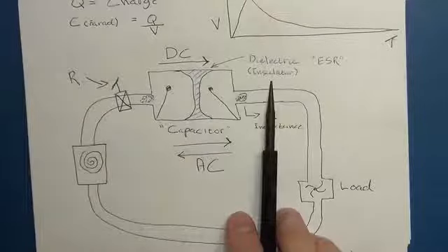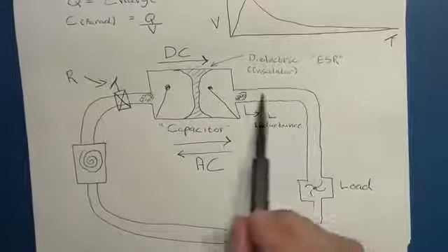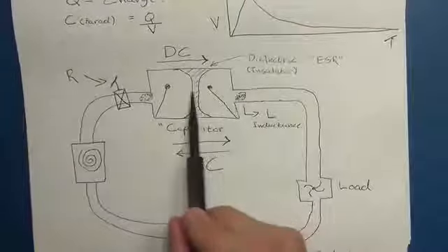What happens if we apply AC, where we've got our alternating current going in two directions, so our pump is going backwards and forwards? Well, then you can quite clearly see that you are going to get current flowing through the capacitor, because with the pump going this way, the bladder pushes current out this way, and then as the direction changes, it's going to flow back this way. The bellows is going to push out this way, and you're going to get current flow that way. And it will allow an alternating current, or a current with frequency going back and forth, to flow.